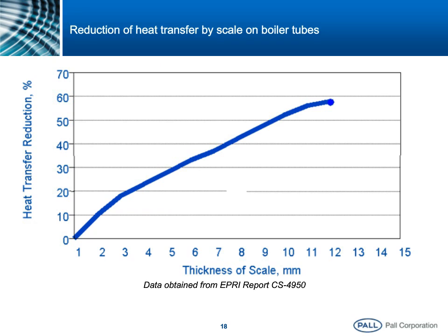And other than the mechanical failures of the tubes themselves, even before that happens, any deposit of scale on the tube will dramatically decrease the heat transfer through the tube. So what ends up happening is you have to burn up more fuel in order to bring the water in the same state that you would if you had a clean tube.